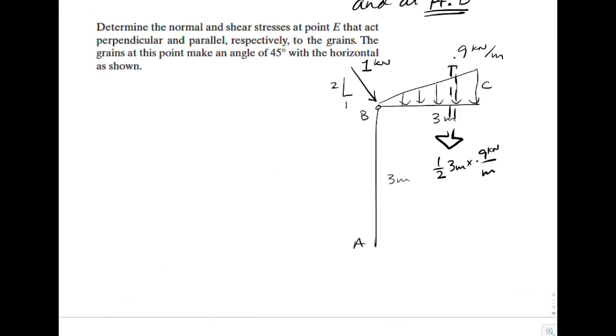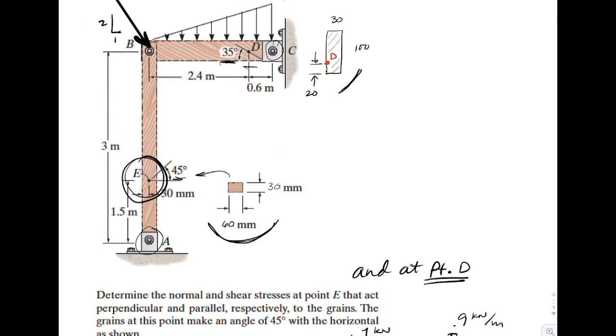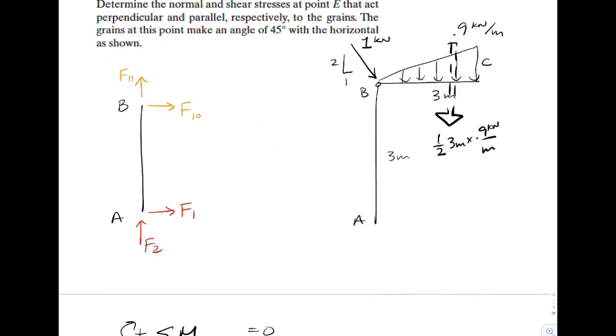So let's go ahead and draw some free body diagrams. We'll draw the free body of the vertical member. And we see that we've got a member that has 2 external supports down at A, and also now exposed internals. I don't have to put the applied load on point B on this figure. You could think of it as existing on the horizontal member free body diagram. But all we're going to do is quickly prove that this is a 2-force member. So if I spin a moment at B, then we find that F1 is equal to 0.